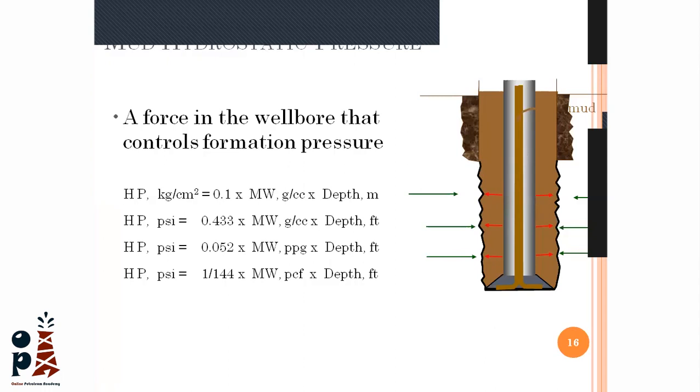When we are talking about the bottom hole pressure, it is the summation of all pressures affecting the bottom hole. For example, in a well control situation, when we close the well, we will have shut-in casing pressure and shut-in drill pipe pressure. So when we calculate the bottom hole pressure, we will consider these closing pressures. Anything affecting the bottom hole, the pressure above or the summation of any pressure affecting it, is the bottom hole pressure. So in the dynamic condition, if we put a pressure gauge in this area, it will sense a higher pressure due to the friction at the annulus.